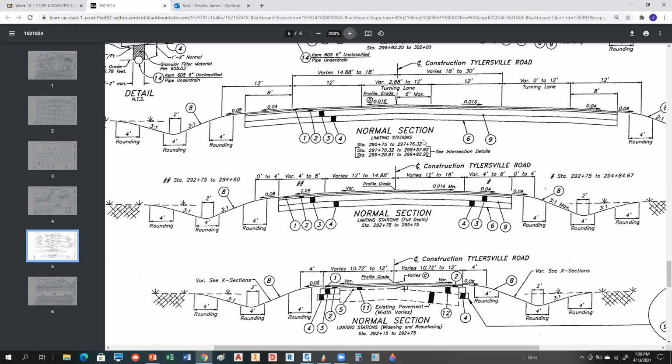So for these kinds of roads, they would usually do it in full sections, not half sections. Yeah. So these are full sections, correct? But if it's a simple subdivision street, you might get a half section because it's just a mirror image to cross it. It's pretty straightforward. Okay, does that make sense?